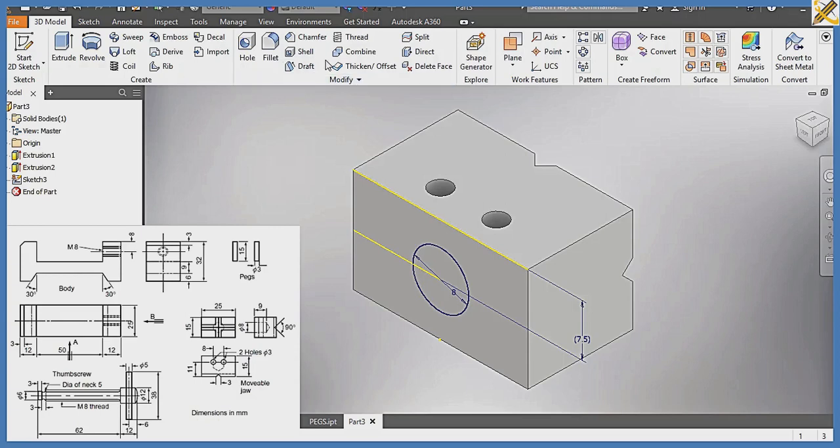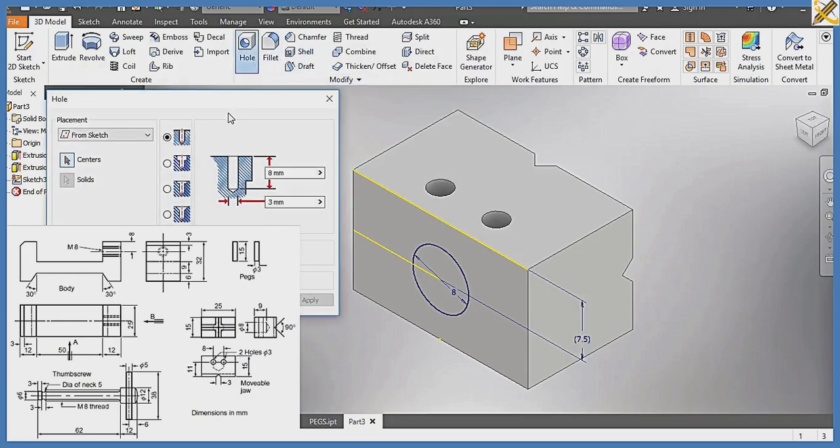So we are going to click on the hole command. Can you see the hole command? So what type of hole do we have here? It is this. Take a look at this drilled hole and the one in the diagram on the screen. You can see that they are the same. This one is a counterbore hole. This one is a spot face, and this one is a countersink face. So we are using this, which is there. This area is to state the height, while this area is to show the diameter.